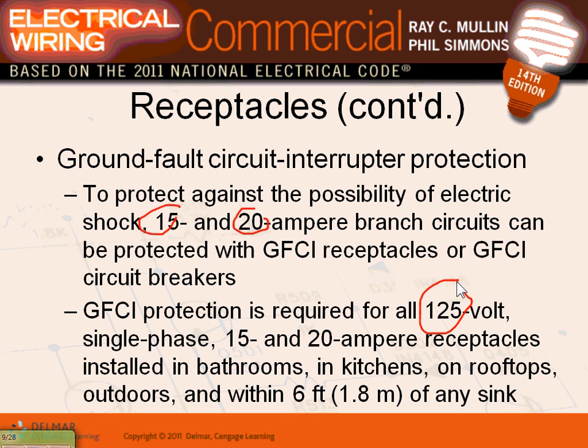So these are the only places, and those would be GFCI. In the mechanical room, since it's concrete and all this stuff, it's a good idea for maintenance to put a GFCI receptacle there too. Any damp or wet location, even if it's not listed, it's an industry standard to put a GFCI receptacle for safety. Any question, guys, about the 20 amp, 15, 120 GFCI receptacles?